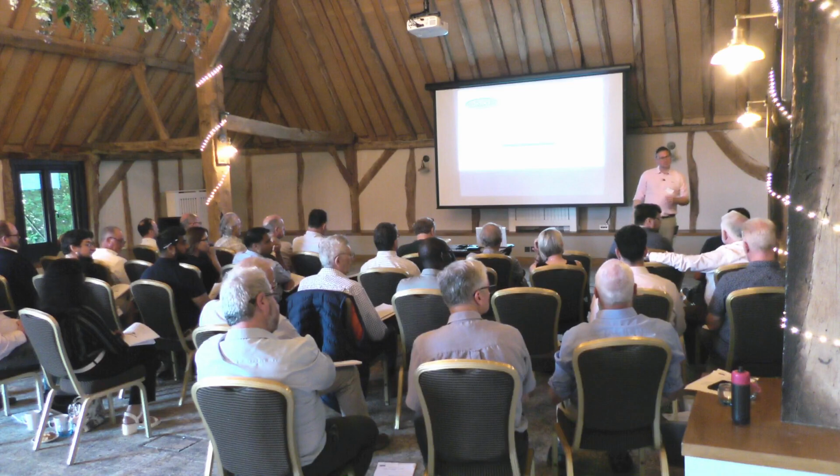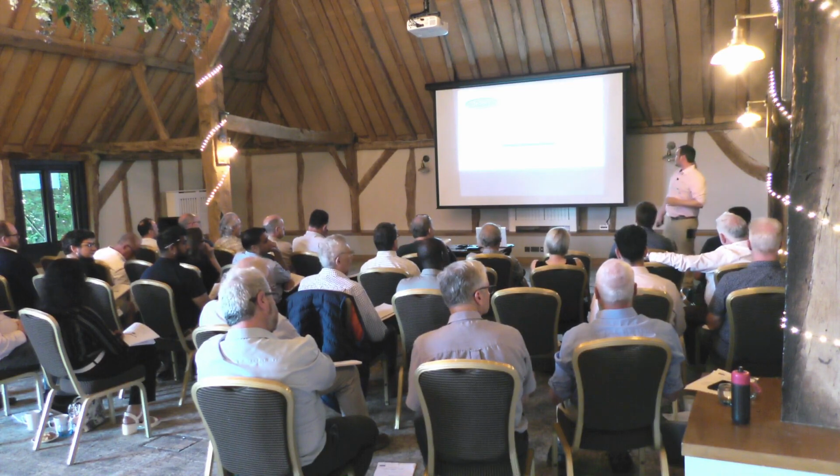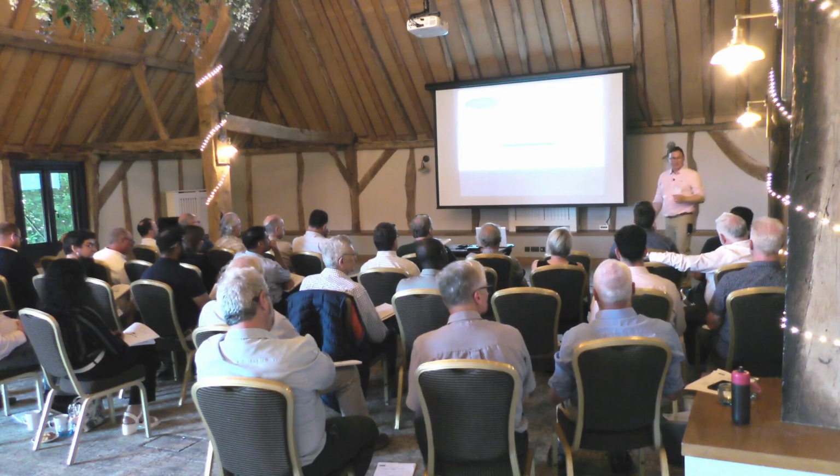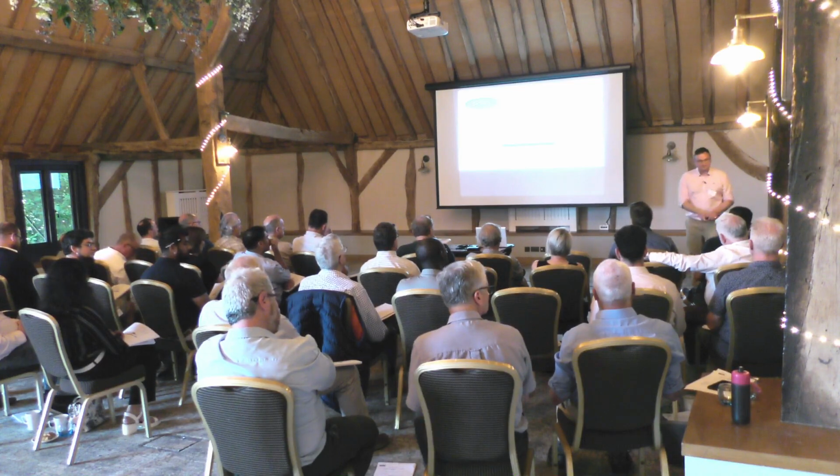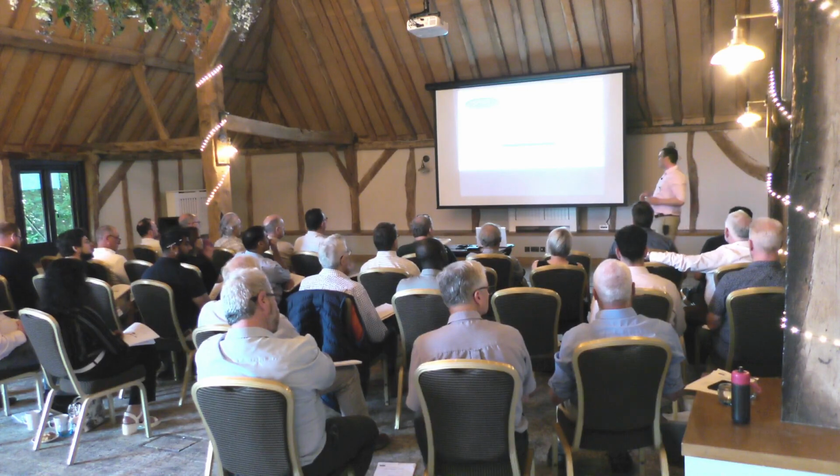Yes? Just in regards to the staircase to that gallery, any considerations in regards to that? In terms of Part K, or? In terms of, yeah, I mean, any... So there's no... Is a ladder, effectively? Well, no, so the stairs would come under Part K, in which case you're looking at ADK guidance with internal risers and all that sort of stuff. It should be suitable for means of escape, in which case Part K would kick in.